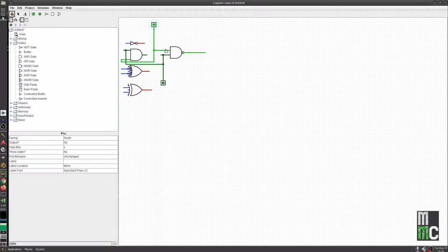This is an AND gate. And this one is active because it's saying both of them are not on, so therefore it's active. If I click this, it'll be the opposite. Now the AND gate is active. You see this turns green because they're both on, and the NOT gate turns off because they're both on.